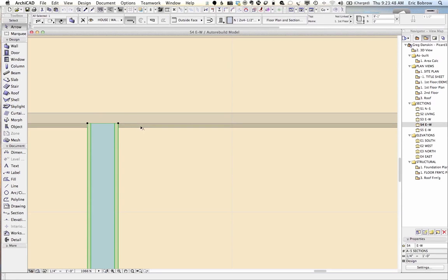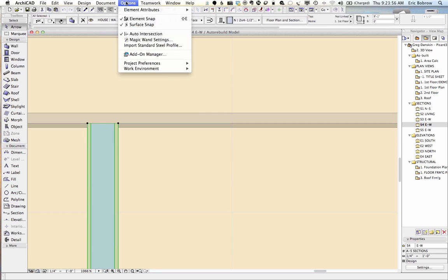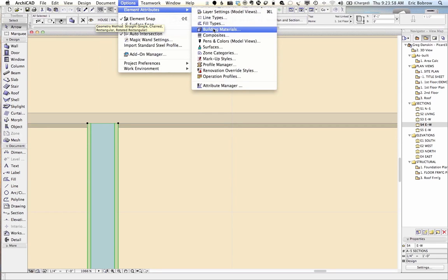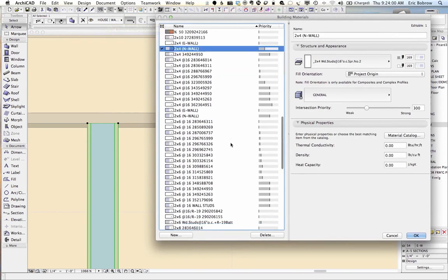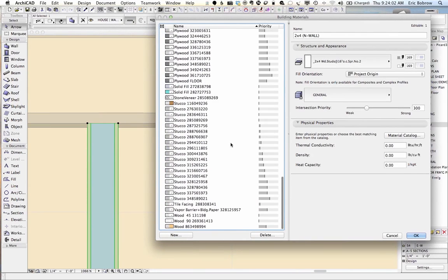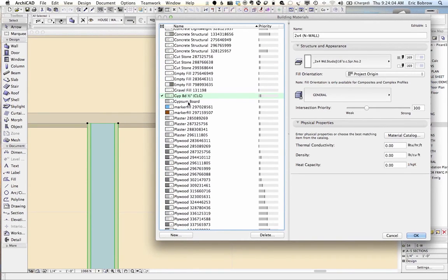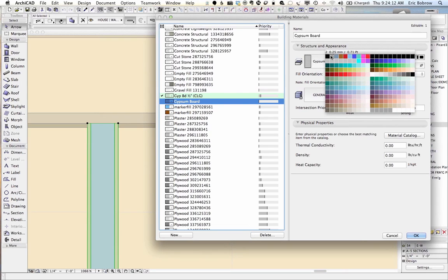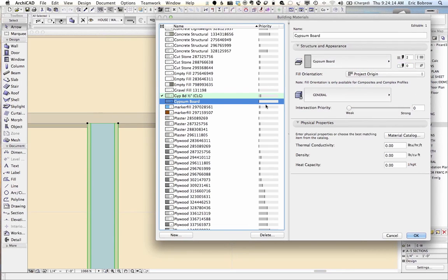Now you notice a slight change that happened here because this particular gypsum board was using one of the deleted types, and it now is a slightly different version. It was substituted with the one, where is it? With this one here, with this black pen. So it became a sort of grayer one here. We can maybe change this to the gray to make it even lighter.